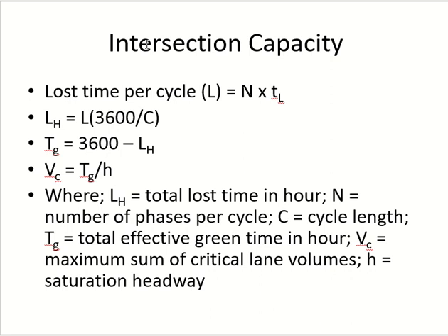Okay, good. But this is taken by which vehicles? If you want to measure it, then you will be looking at which vehicles? No, before the fourth. The loss time is before the fourth. So the first 3-4 vehicles take some extra headway. That extra headway is startup loss time. Yes, it is in green, but it is not all green. I said it. You will write in the exam and then you will say, Doctor, you said it. So I'm telling you, it's not all green.